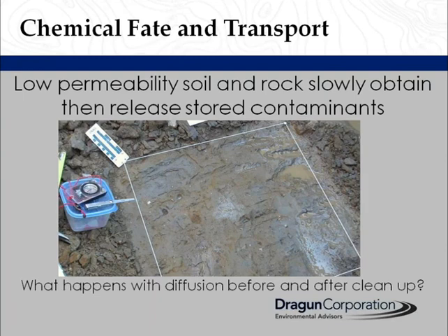So if you go in here after, say, there's a contamination release, and try to clean it up, many times the cleanup effort is focused on getting the easily obtainable water, like the water in the fractures, but not the contaminants that are in the clayey soil, the matrix. And after you finish your cleanup, often what happens is the chemicals that are trapped in the clayey soils come out into the water, and you get a recontamination.